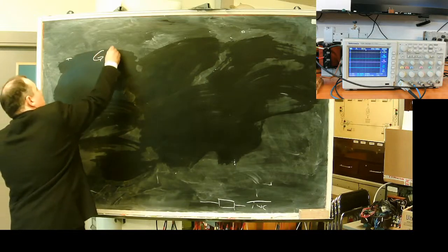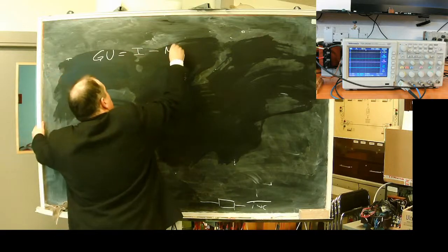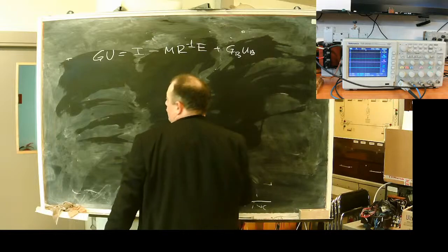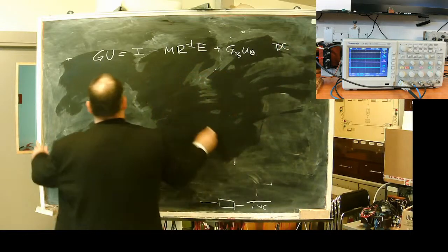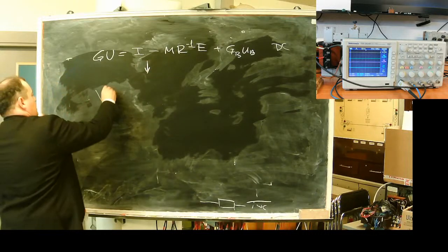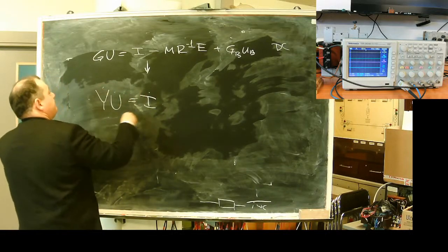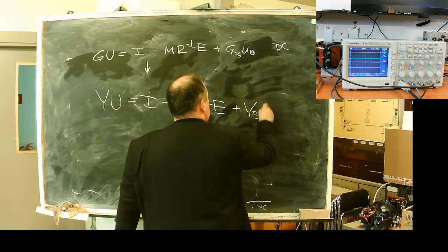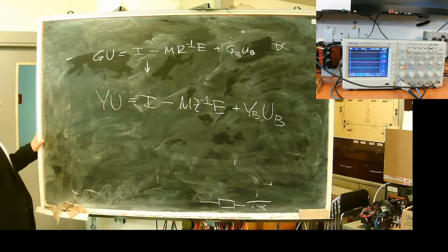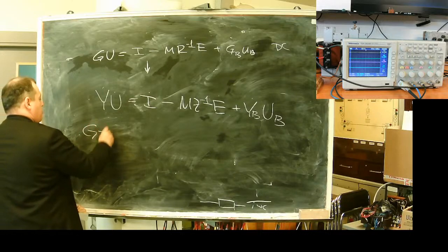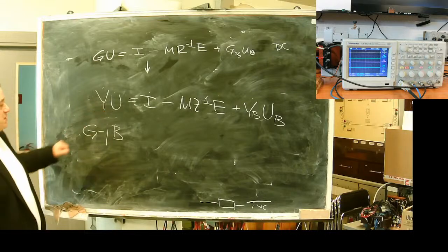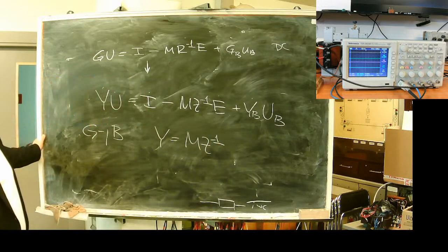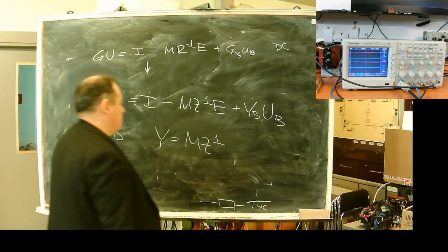The nodal voltage equation for a DC network will become the same, where Y is the nodal admittance matrix, calculated as the inverse matrix of resistance, or if you prefer the matrix of impedance, transposed,